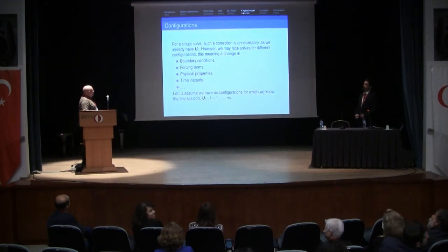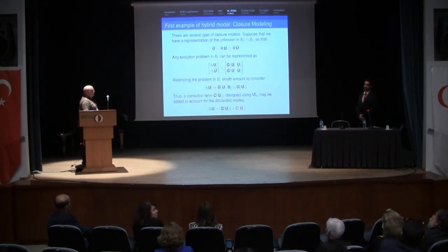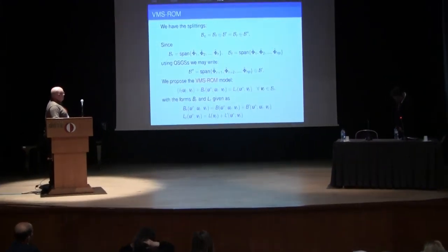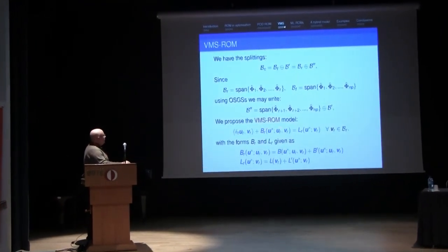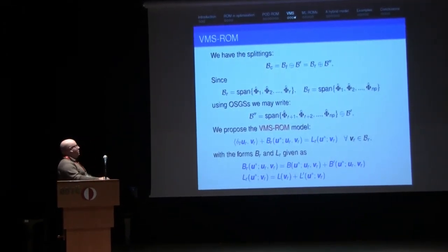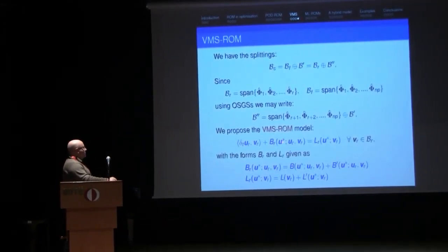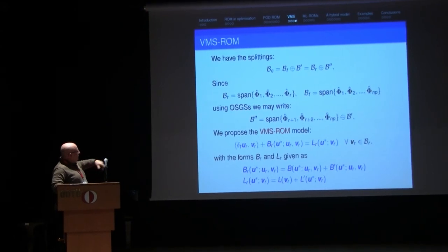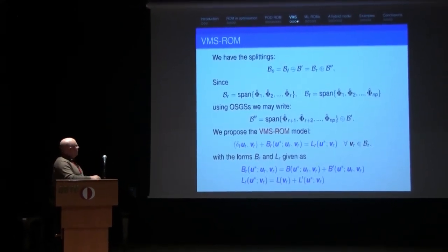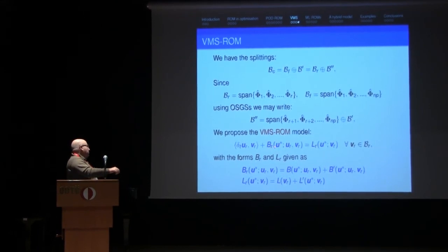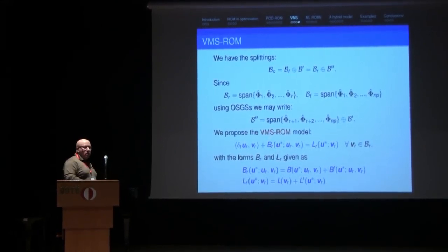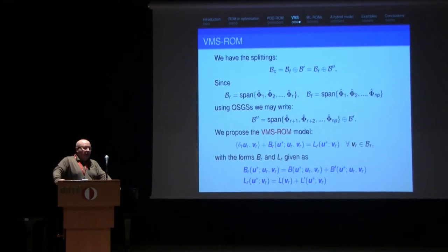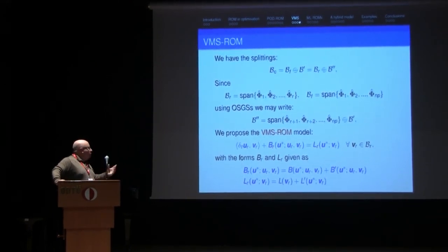I haven't mentioned that, but the cost of this system, the reduced system, is in fact similar to the cost of the full order model because of the nonlinearity. So what discrete empirical interpolation does is to bring back the cost of this system to that of the reduced order model by doing what is called hyperreduction. So you further reduce this term to make it cheaper. But they and other hyperreduction techniques aim at reducing the cost due to the nonlinearity.